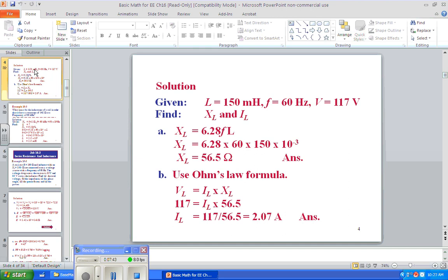Shocking, I tell you. Okay, and by the way, the math book likes to use V, that's the electronic symbol for voltage. But we always use E. It always annoys me when I see the V on the things. But anytime you see V on a quiz, it's because I didn't catch that I used something out of the math book that still had the V on it. Just assume that that is E instead of V. Okay? So 117 divided by 56.5 ohms is 2.07 amps.